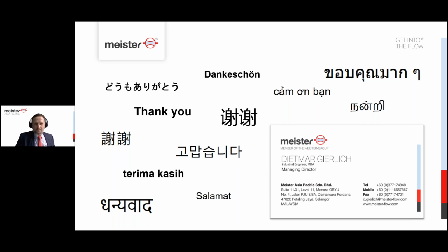Okay, so next question is from Sabrina Ng. Is your flow meter material suitable for chemical medium? That's a good question, thank you. Basic, easy answer is yes. As we have in our catalog 2 standard materials available. One would be the brass option, and the other one is the stainless steel 316 Ti.